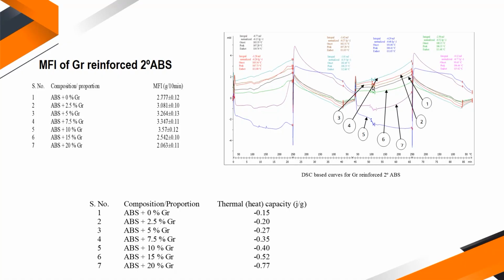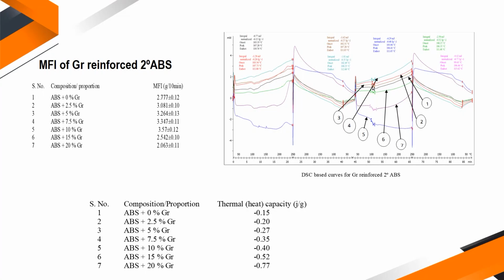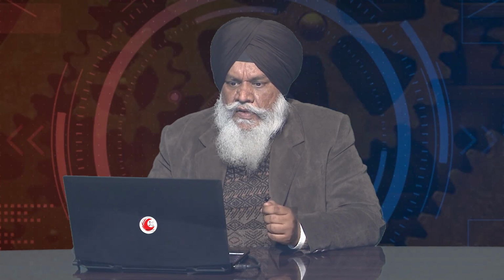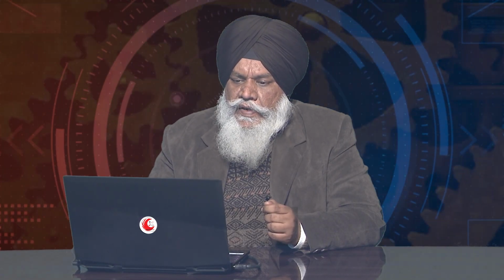We then tried to see the thermal properties, how they affect the melting temperature, then the glass transition, the crystallinity behavior, and the enthalpy. What we observed is that as I increase the graphene proportion, the heat capacity, represented in joule per gram, increases. Of course it has to, because graphene is one of the best conductors.